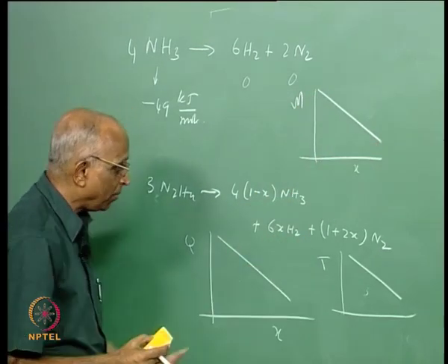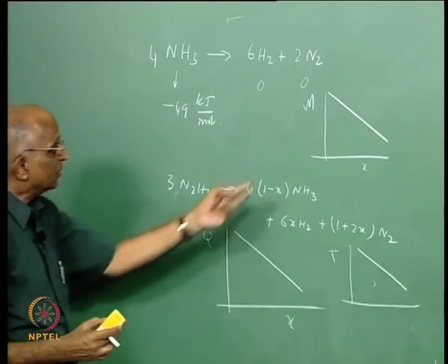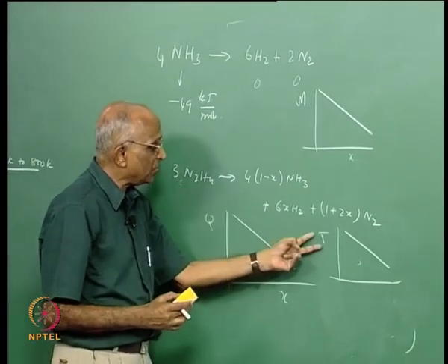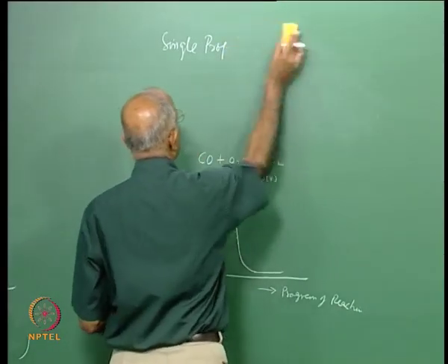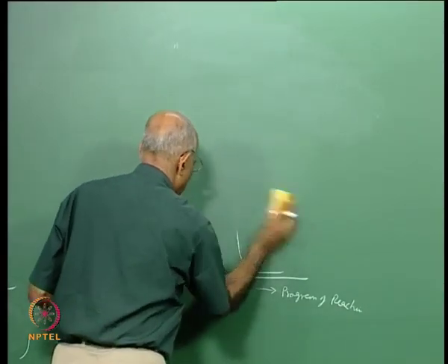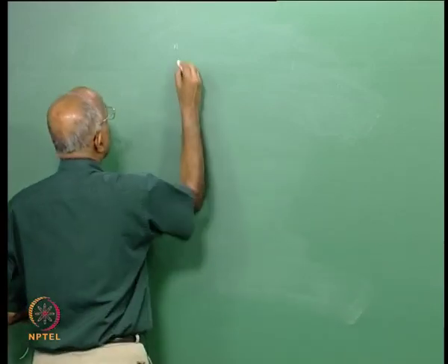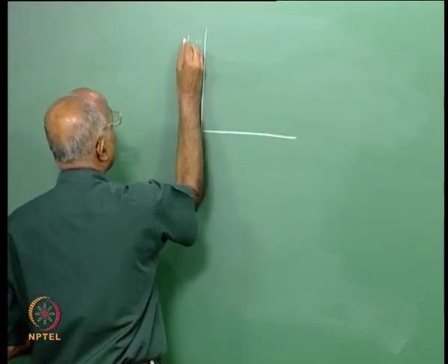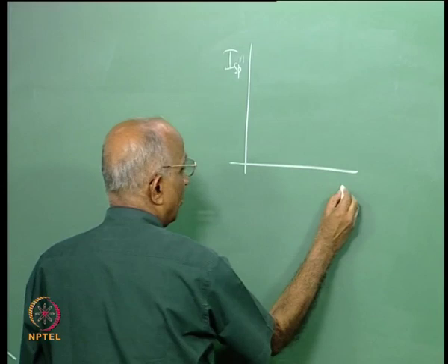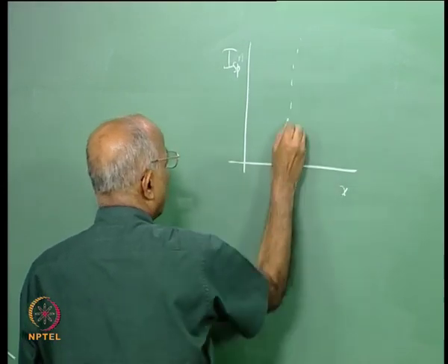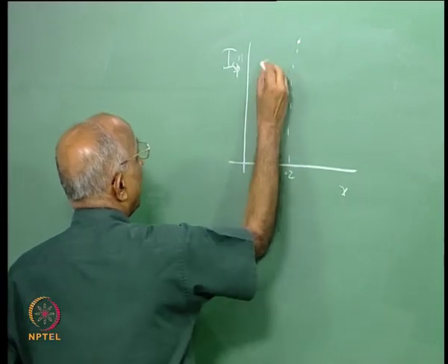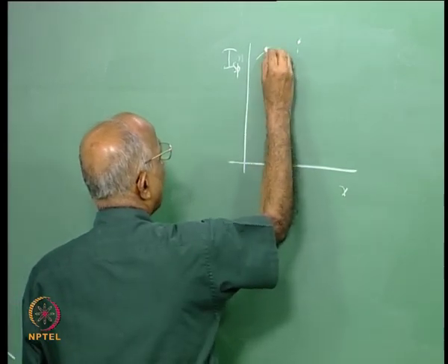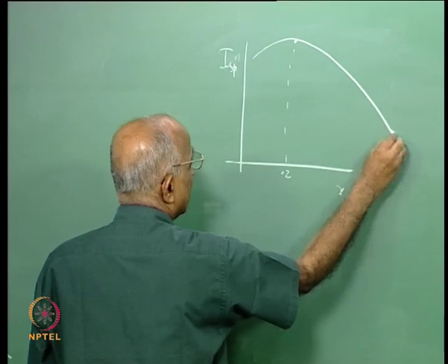I give a homework problem on that. Since molecular mass comes down and temperature comes down, if I put both of them together in terms of either C star or specific impulse, I find my specific impulse with respect to X is maximum at a value around 0.2 dissociation, and then my Isp goes like this and keeps decreasing.